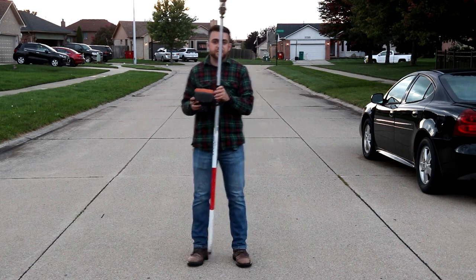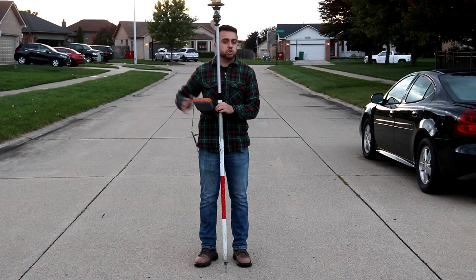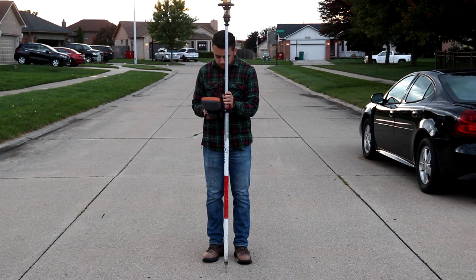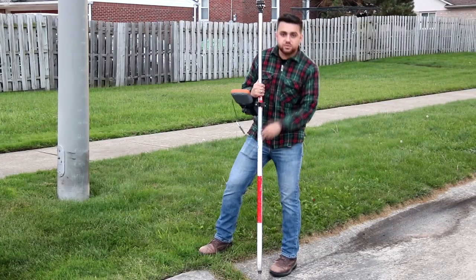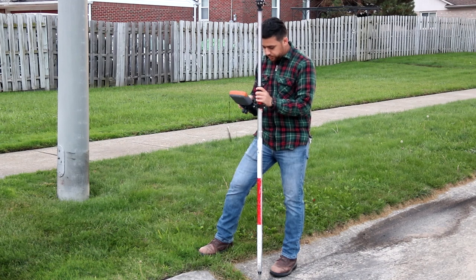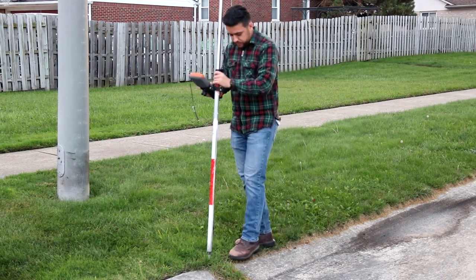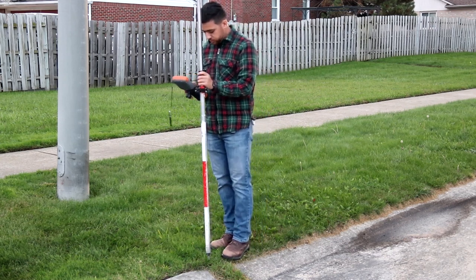All right, now I'm at the center line of the road. This will show me exactly where water might be going or just the sloping of the road. So I'll just code this center line road 1. Perfect. On the other side of the street, I have another curb and gutter. So I'm going to create a new gutter line. This will be gutter 2. Okay, take the top of this. This will be my curb shot, and this will be curb 2.